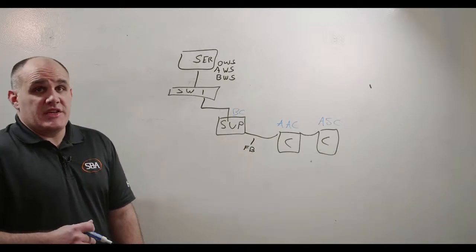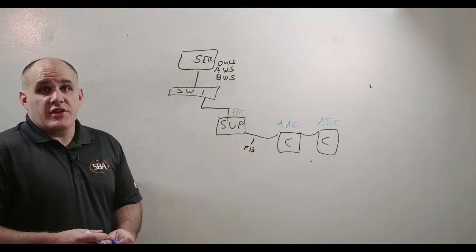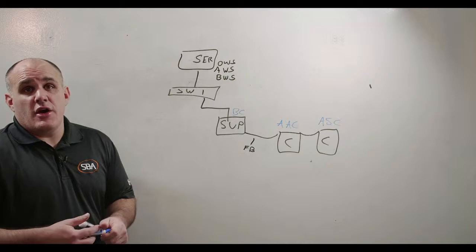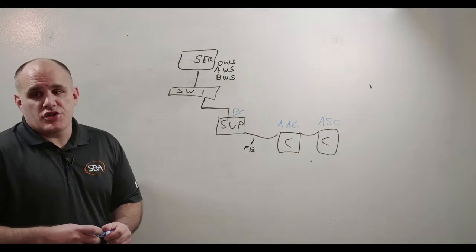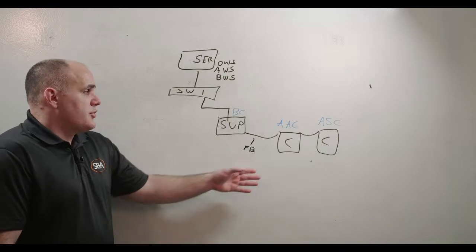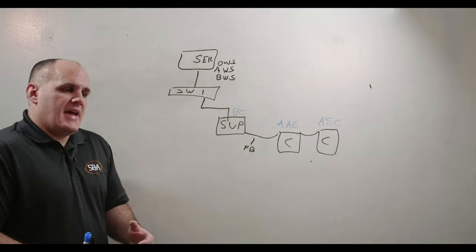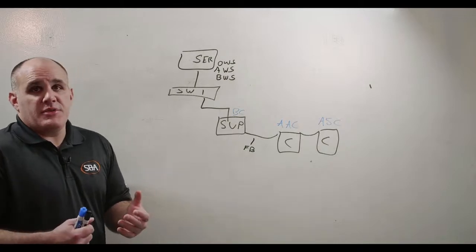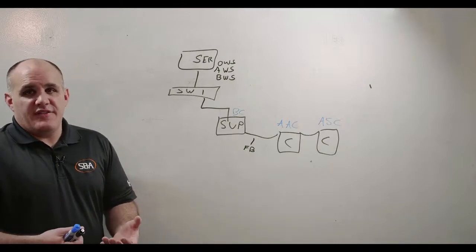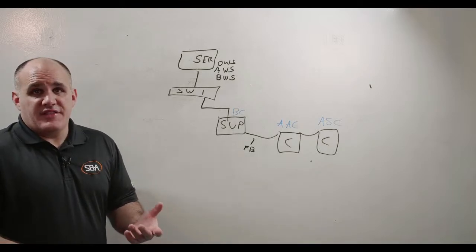That would be the 3 tiers, right? You'd have a supervisory device, you'd have a serial network going to your field controllers, and then you'd have your I/O. This is very common of commercial office buildings where maybe you have a supervisory device or an advanced application controller sitting on a rooftop unit, and you've got like 20 VAV boxes, and that's it. That's all you got. That's a very common architecture.